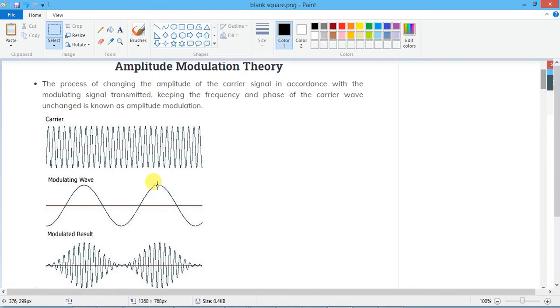So that is this voltage, the amplitude of the modulating signal, Am, divided by the amplitude of the carrier, Ac. So the modulation index is Am by Ac. The range of the modulation index is 0 to 1. 0 means no modulation, and 1 means 100% modulation. I think here it is almost 100% modulation. If it is less, then you will get a little bit like this here. That will show in the simulation.